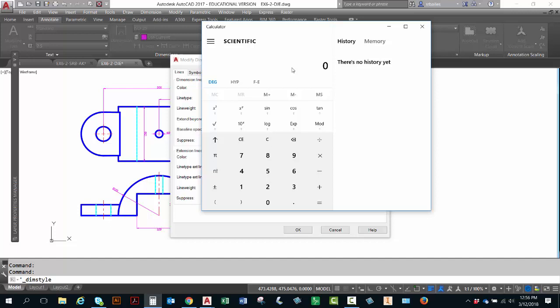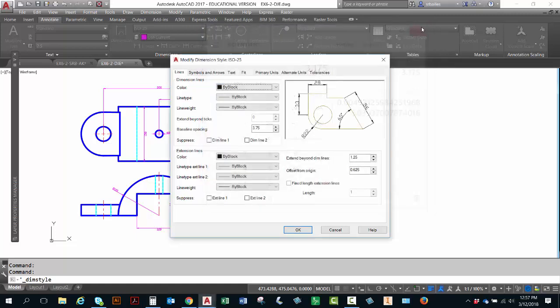Okay, so if I take 1/8 inch, for example, is a common value we use in dimensioning setup, and multiply by 25.4, 0.125 times 25.4, you have 3.175. So generally I round that to 3.2, and then anything that's a 1/16, it would be 1.6, and so forth.